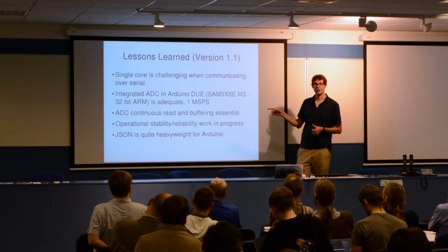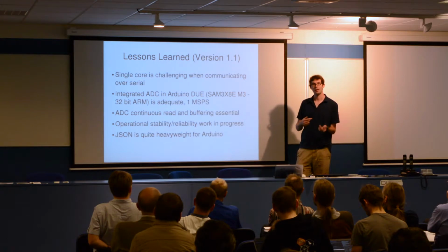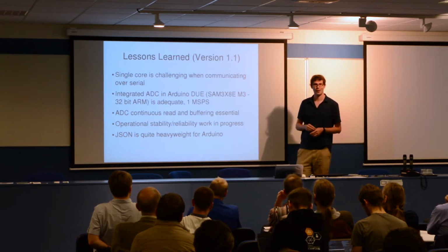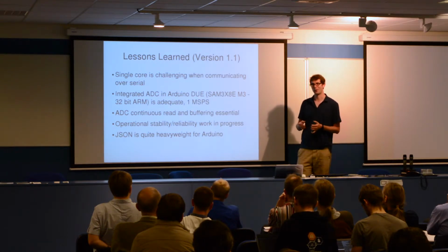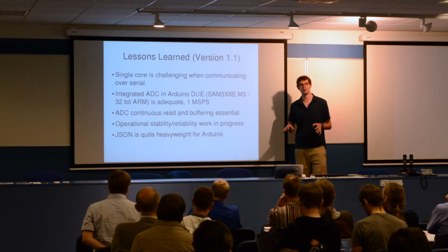It's just about enough to read the signal in. The key innovation we've done so far is setting our ADC into continuous read mode and then buffering it. So effectively this allows us to read back when we get an event. It probably sounds trivial, but it took us a very long time to come up with the idea of doing it like this. We're now working on the stability of the code.